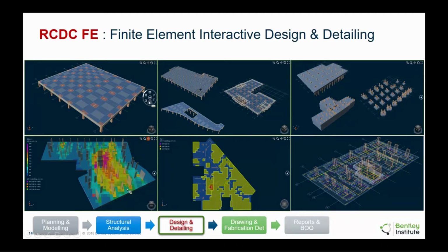detailing exercise. What you see on the left is a reinforcement required contour. So this is basically telling you that at a given location, say bottom X, in a given direction, this is the distribution of reinforcement that you need to provide. So you can actually see the heat map for that. And as you start providing the actual reinforcement, you will see they get more blocks. So the blue is, let's say, the mesh all over. Somewhere locally I'm providing extra. So this is the first iteration.